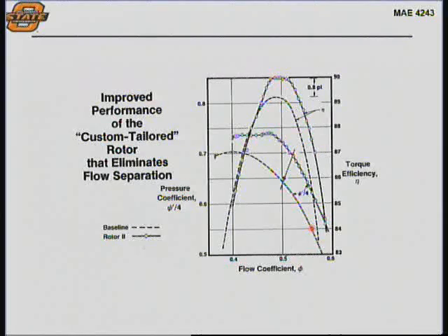You close the back area that's flowing through the machine, and you measure what the pressure rise is. As you continue to close, you move along this line, and so this is a constant speed line. At some point, it'll stall, and that's what this point is here. So think back to that compressor map I drew last time, and this is one of those constant speed lines, because we're only talking about one stage here.